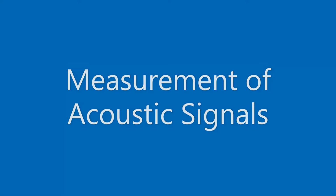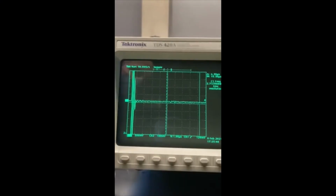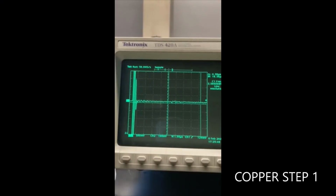So we have demonstrated how the thickness of the sample changes the transit time and hence the time difference between the pulses. Now we will demonstrate the specific measurements for the copper sample on the oscilloscope. On the left side of the oscilloscope screen, you can see the pulse that's created by the transducer. Once the transducer is put in contact with the copper step, now you can see the separate reflecting pulses as they go back and forth through the sample.